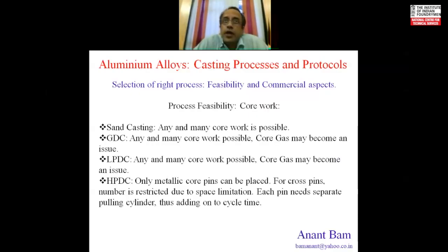Core work: every casting or component needs some interior portion, interior geometry, for which we place a core. For sand casting, any and as many cores as needed are very easily possible.